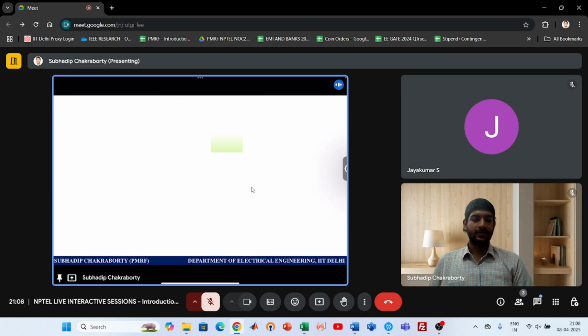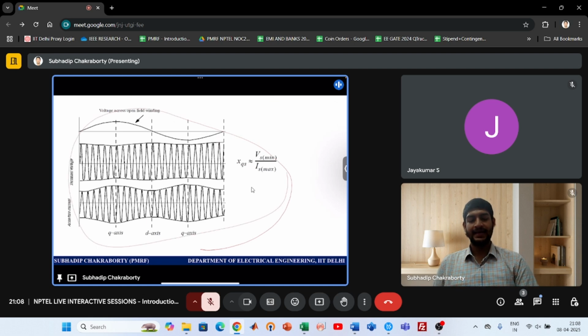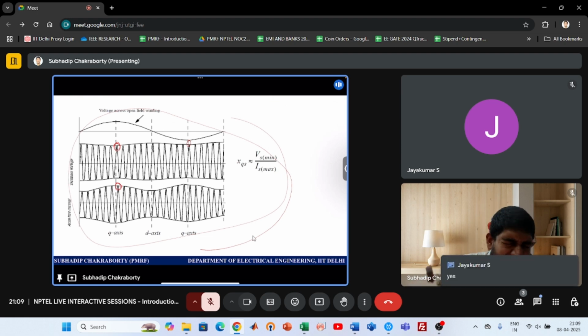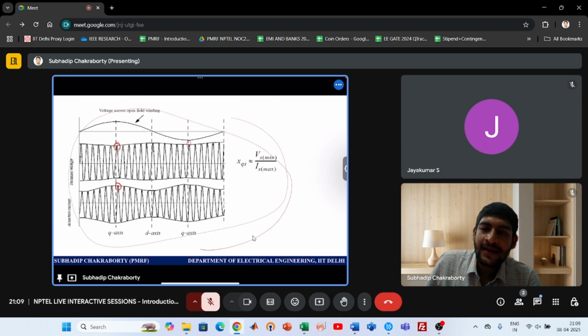So this is what we were talking about. Some drop along the D axis, it is a lesser drop. Along the Q axis, it is a higher drop in voltage and more current, right? So slightly lower voltage and more current, and again, based on the slip voltages, it is appearing. The position of the rotor with respect to the coil, it is happening, right? Because there is R, there is X also, but generally it is what I can say.